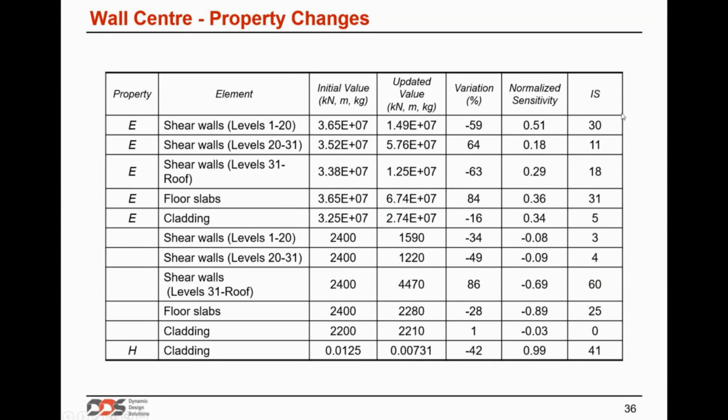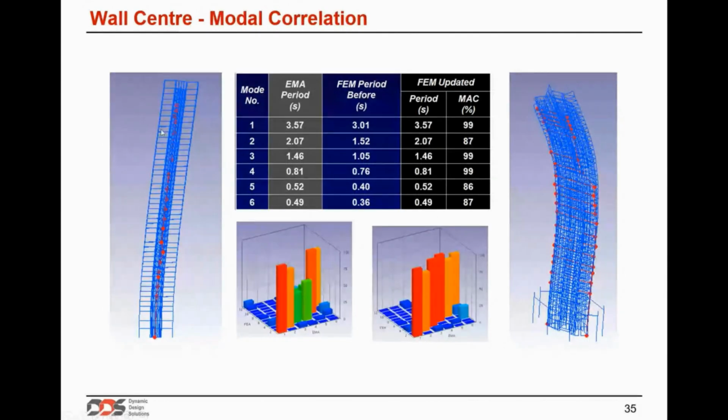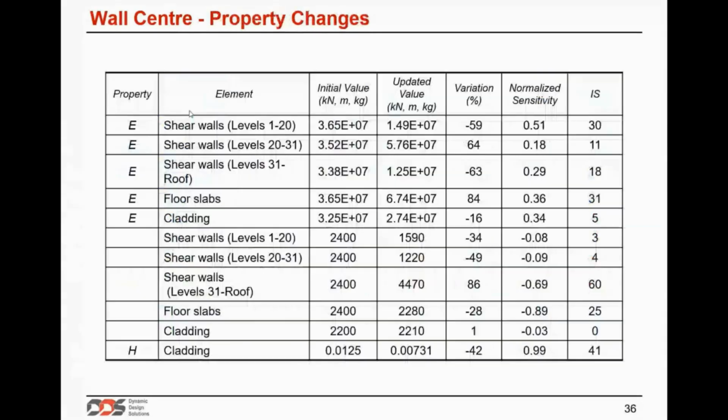But what was observed here is that the variation that is needed can sometimes be very, very big. This is because the finite element model is really a very coarse representation of the true structure. Because everything uses beam elements, the properties are very much equivalent properties that are estimated. It's a bit similar to the aircraft beam model that represents a wing.